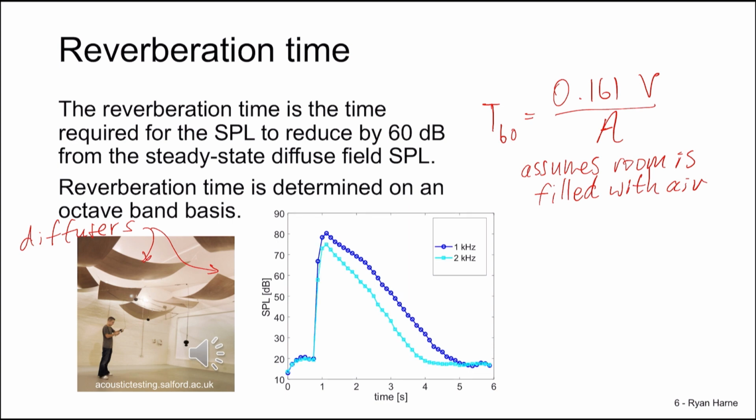If we did this for higher frequencies, what we see is that this slope is a little bit steeper, whereas for lower frequencies, the slope is slightly more shallow. So the reverberation times for lower frequencies tend to be greater. We especially see this at 250 Hz. And the slope for 4 kHz is much more steep.